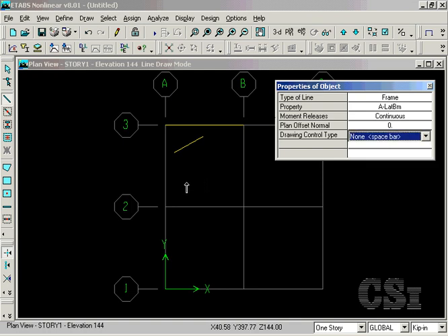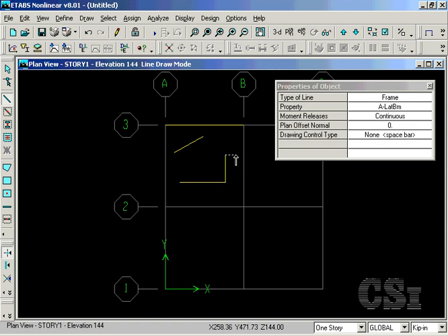If we hit the X key while drawing, the line will be parallel to X no matter where the cursor is. Similar control if we hit Y or A. Note that the angle is 45 degrees. And L, which draws a fixed length element.